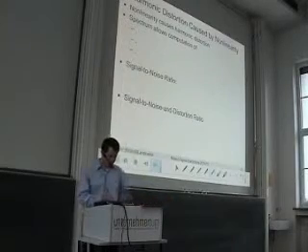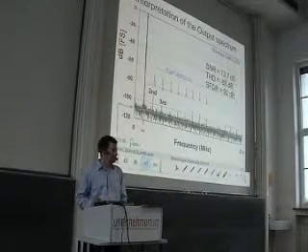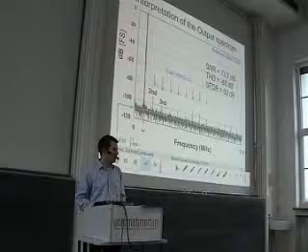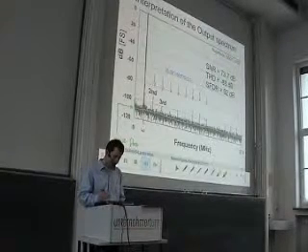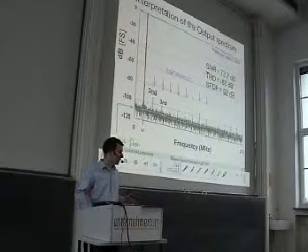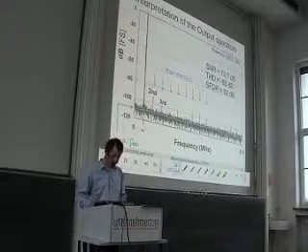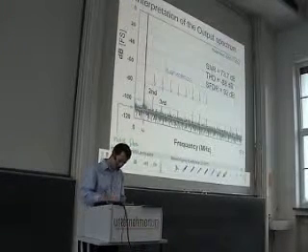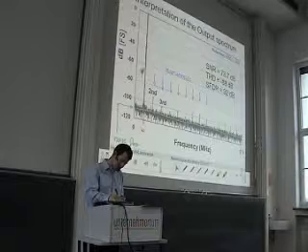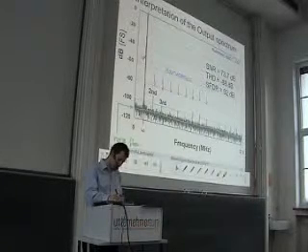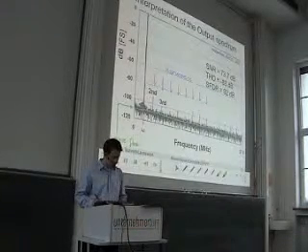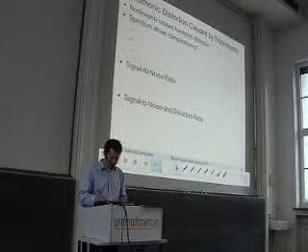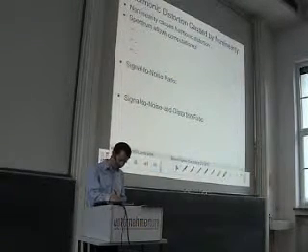We can calculate from this plot the signal power, because we can take the values that we get from our FFT, we can integrate in this region around this spike, sum up the values here, and there we end up with the signal power. So we get the signal power.